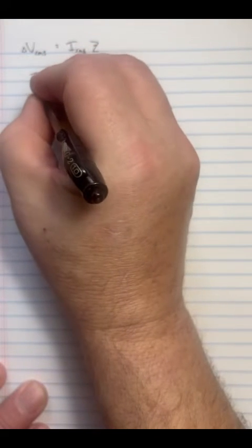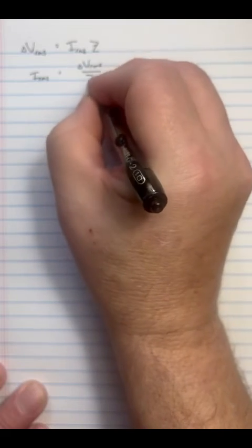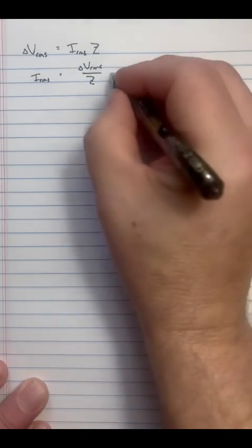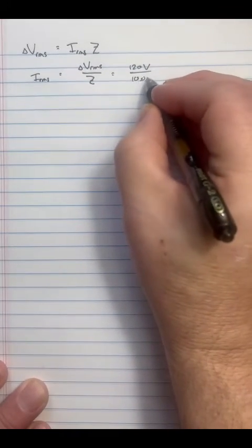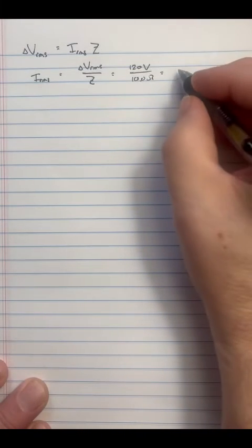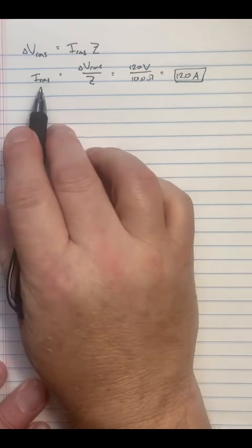All right, we're solving for RMS current. So that is RMS voltage divided by impedance now. The RMS voltage was 120 volts. The impedance was 10 ohms. Yes, I did that on purpose to make this easy. 120 divided by 10 is 12. So 12 amps, and that is RMS current specifically now, isn't it? So interesting that that comes out that way, but that's how this works. So if I want to find or relate RMS current to RMS voltage, I need to go through these steps.